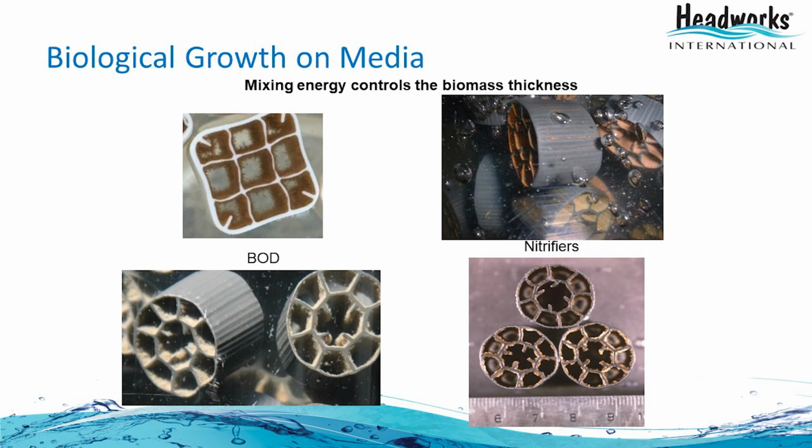This is the BOD removing microorganisms, and on the right there are nitrifying microorganisms, and these films develop on the internal surfaces of these media. These media are made up of HDPE, high density polyethylene, which is plastic, and you can see pictures of the media, and there are different shapes and sizes of the media, and these are the core offerings of Headworks International, the company that we represent.